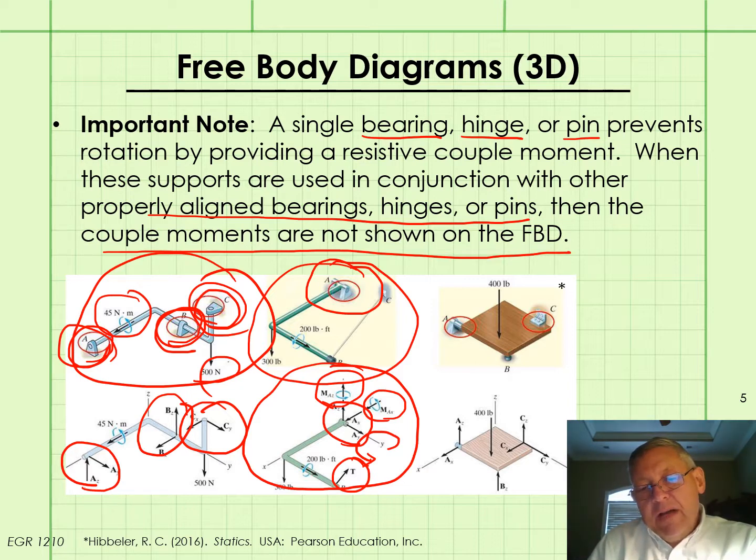We have 5 at the pinned support, but then only 1 additional unknown, and actually we would need to know the direction of T in order to keep it to 6 unknowns and be able to solve with our 6 equations.